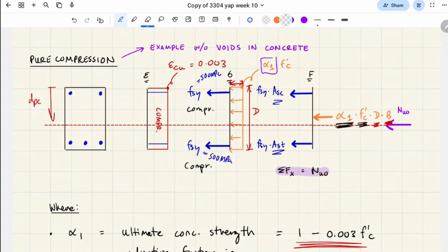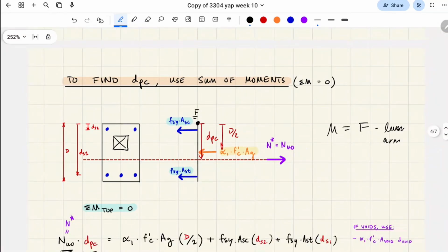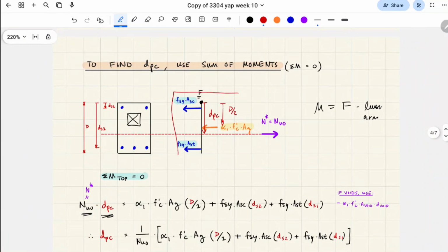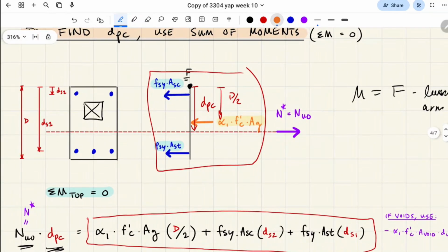Actually, I'll show you on the diagram below because it's more like an equation. What would we do with this formula? So basically, here on the right-hand side of our formula, we've done each of the forces multiplied by the lever arm, right? And so for the concrete component, that's this, right? What would we do to account for this void in the concrete if there was one? Don't need to do anything.